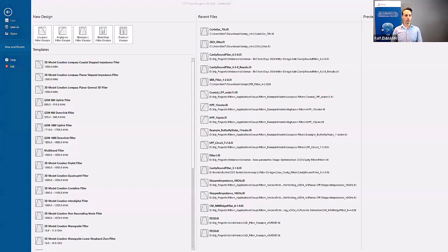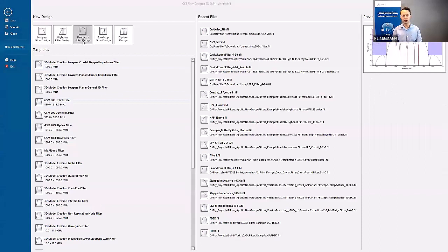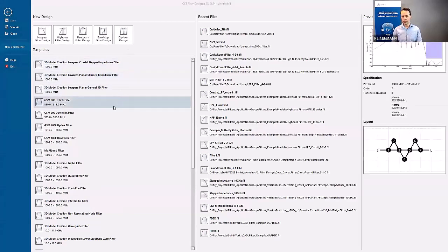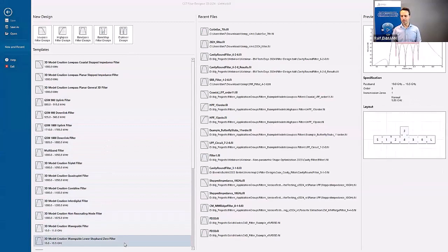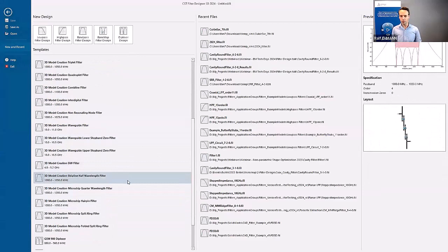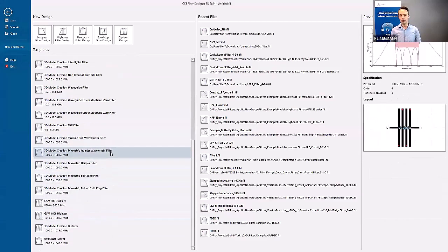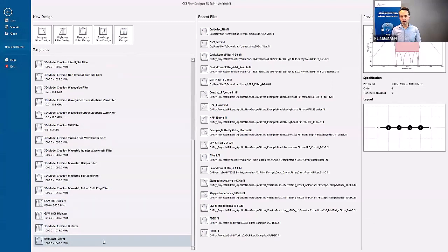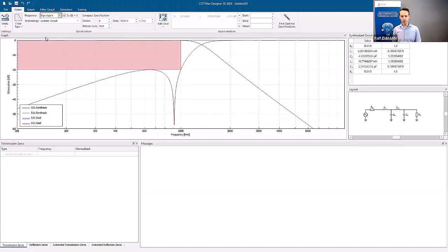responses. So you will see there at the top, we can select between low pass, band pass, and even diplexers in the end. And one can also find a couple of different example templates here. This is a good starting point if you are new in FD3D, and you can see that some contain synthesized networks, while others, full models with various implementations. You see the planar stuff here, there's cavities, and even some diplexers as well. Now, let's get started by just selecting a low-pass filter response.